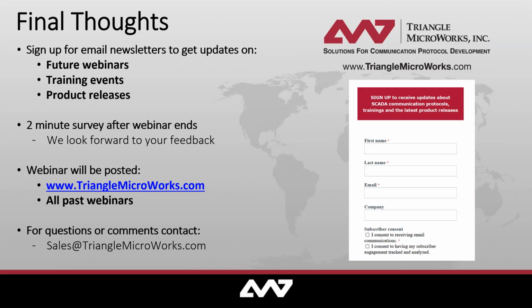The key goal with unit testing, the way we see it, is that you make sure that the basic configuration is correct, because a lot of trouble sometimes comes from something not being configured correctly, and it's easier to find that on a single device than in the whole system. So it's really to make sure everything is configured as you have it in the file, and as such, it needs to be done before you have everything connected. Hope that answered the question.